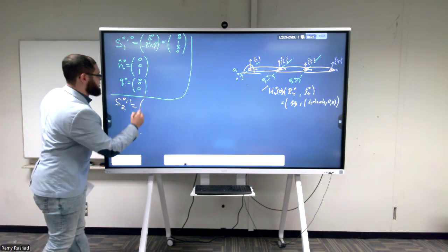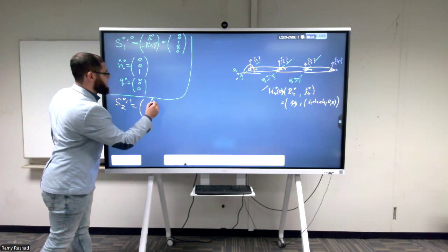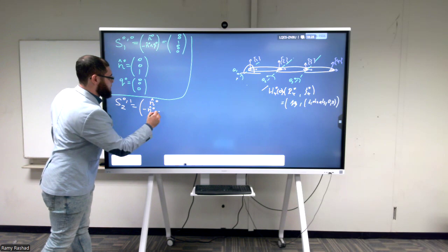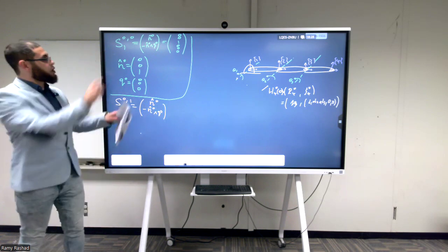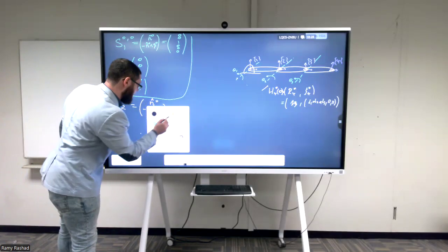It looks like this because it's also a revolute joint. So it's some n hat expressed in the 0 frame and another n hat cross with the q0. Again, these are different n's and n hats and q's. To be proper, you have to define it like this.